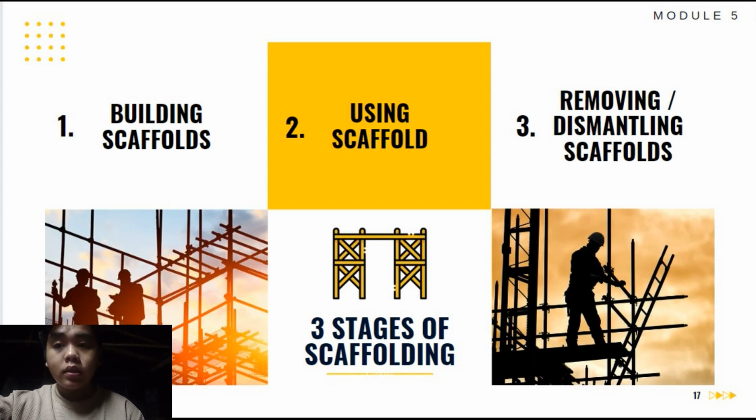Platform ends: each end of the platform, unless cleated or otherwise restrained by hooks, must extend over each support by at least 6 inches. For upper scaffold access, provide access when scaffold platforms are more than 2 feet above or below the point of access.